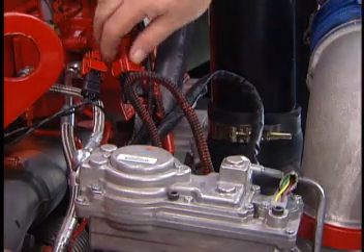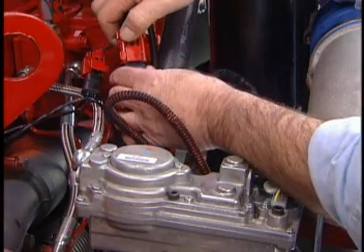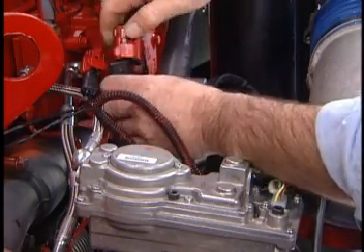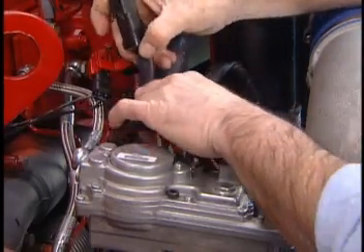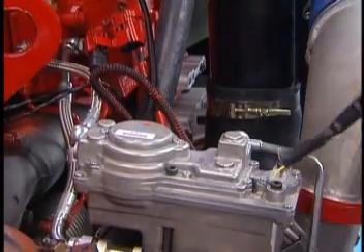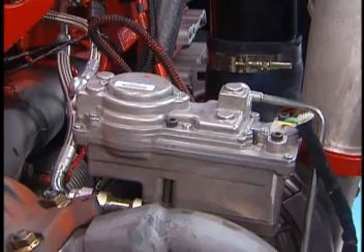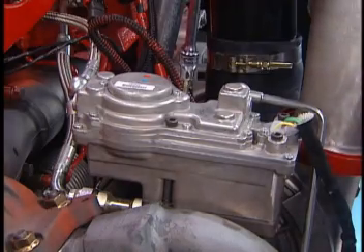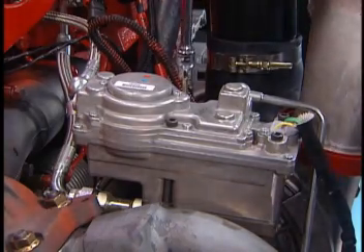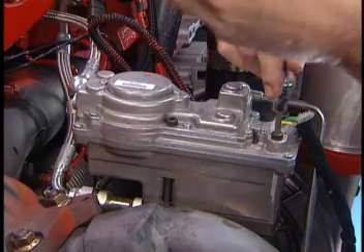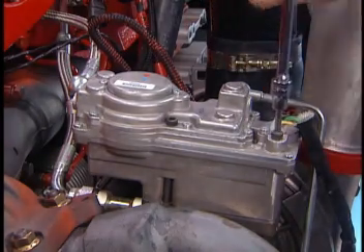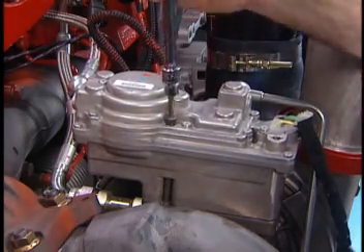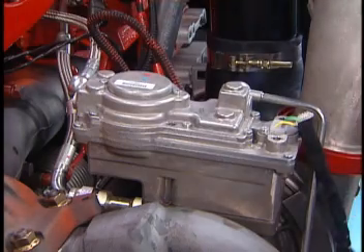Disconnect the wiring harness from the turbocharger actuator by sliding the locking tang to the open position, then pushing down on the release lever and pulling the connection apart. Loosen the cap screws holding the actuator to the turbocharger bearing housing. Remove the loosened cap screws and actuator.